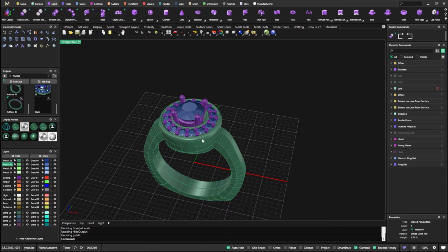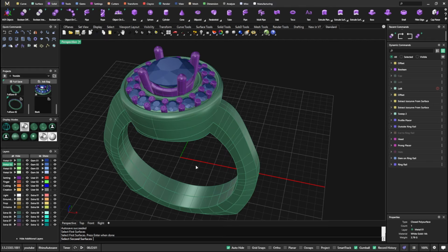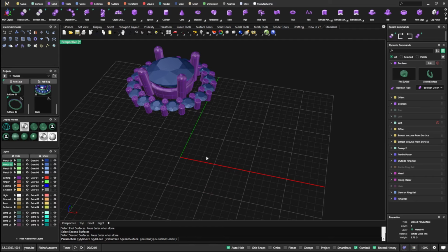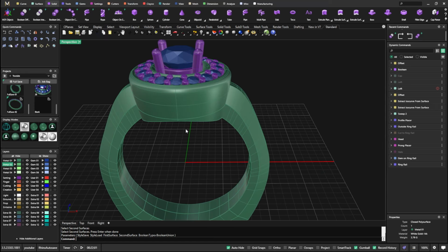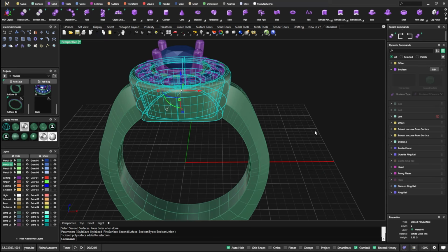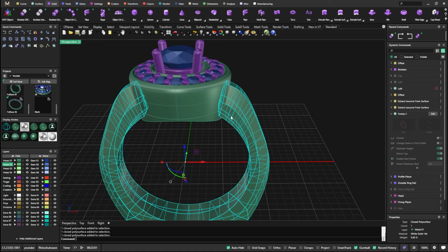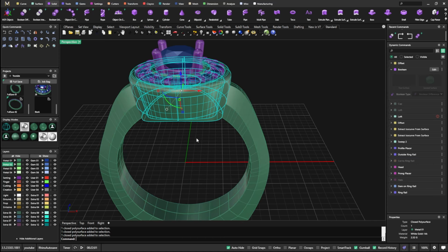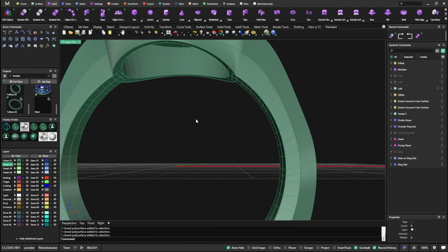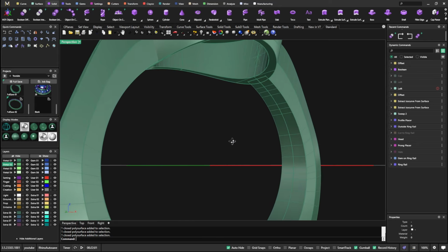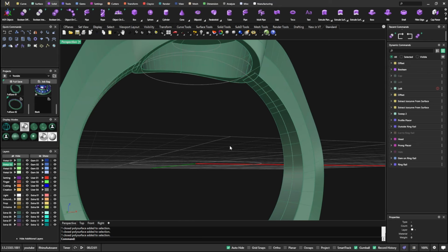Now at this point, I think I am going to go ahead and Boolean union this surface here, enter, this surface here, enter, and it blew up. Something's not correct. Maybe there's, oh, there probably is because it has a seam. Our halo's closed, it says okay, and this is closed, but we're still getting some kind of messed up item there. So let's turn back on our curves here real quick.